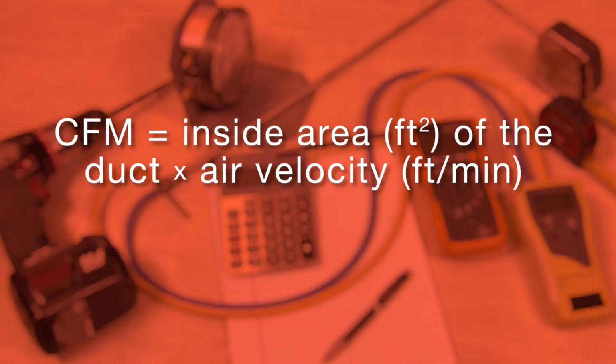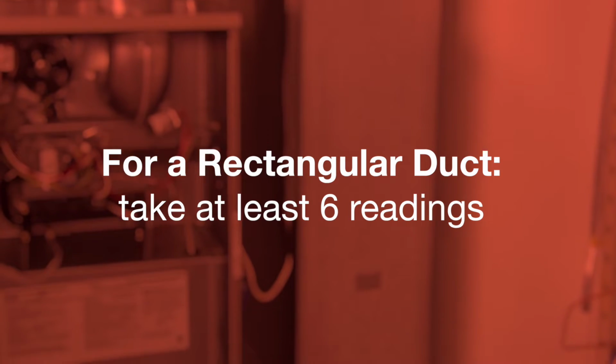CFM is equal to the inside area of the duct in square feet and the velocity of the air in feet per minute. When multiplied together, the result is cubic feet per minute. Accurate airflow measurement requires the velocity readings to be taken in multiple places in the same cross-sectional area of the duct. This is because the velocity profile in the duct is slightly different in each part of the duct.